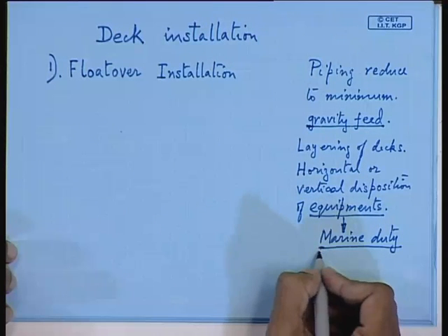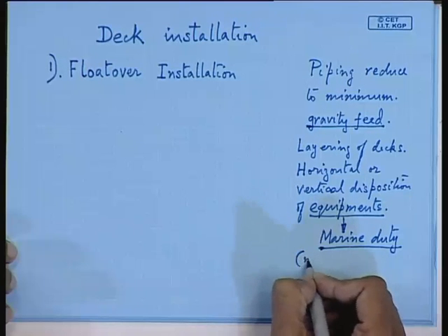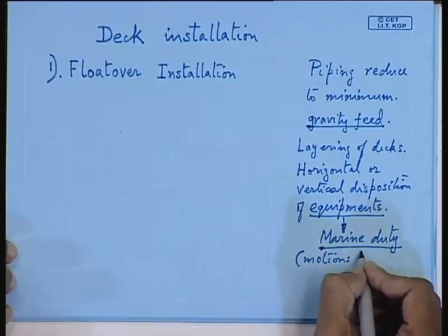Now, marine means the ships will have a lot of motions when going in the seaway. Now, the sump of the engine has to be designed in such a way that the engine can take air whenever it is having rolling, pitching and all these motions. So, in offshore platforms also the same thing will come across. So, here these equipments are to be designed for marine duty. Now, the main thing is motion, which has to be taken care of.